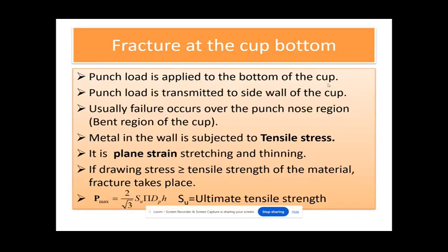This maximum load can be determined by using this expression. Pmax is given by 2 by root 3 into SU, ultimate tensile strength, into pi into dP, where dP is punch diameter, into height of the cup.